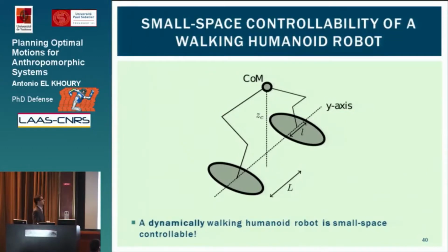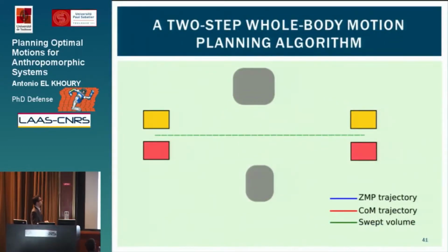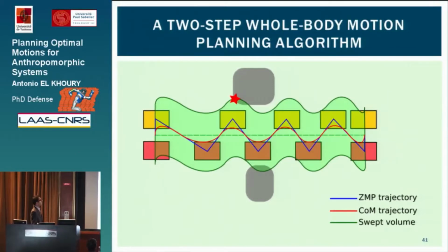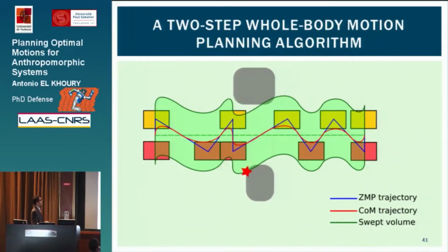Now that we have this property, we can actually, starting from a sliding path, where I show here the original center of mass path, start by executing steps with any length. Now, of course, since the center of mass deviates, when we rely on a pattern generator, as I showed earlier, we might have collisions that will occur. So now that we have collisions, we can actually cut the path in half, keep the parts that are collision-free, and then start again.